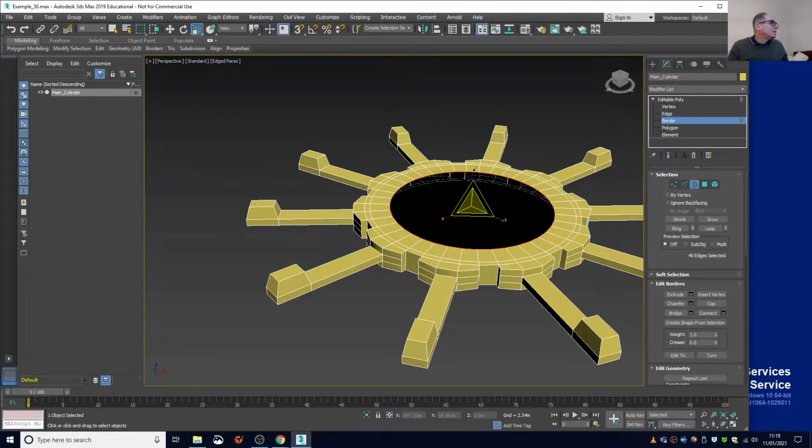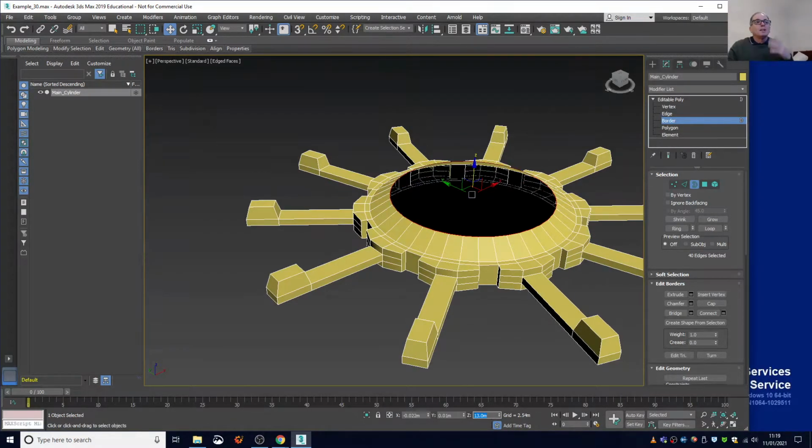And so we're going to move the edge. So we go to move, and this time in the Z axis, instead of having 8 meters, we're going to put 13 meters. We can type this here directly, or we can move it here. So we can move like this, just on the Z axis, or we can leave it to 0. So 8, and we want to put 13. So we put 13 here, and we enter. So that's our new shape.